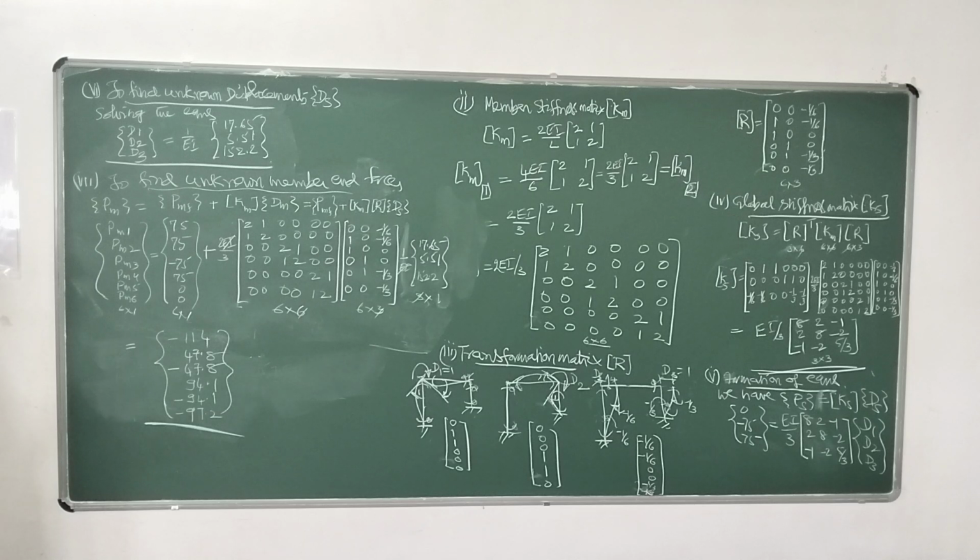The same procedure we have followed in the beam analysis as well as settlement. Beams are non-sway, but due to settlement it is sway, but the sway is known. The settlement value will be given, that's why delta was known there, and that's why we treated these as non-sway beams.